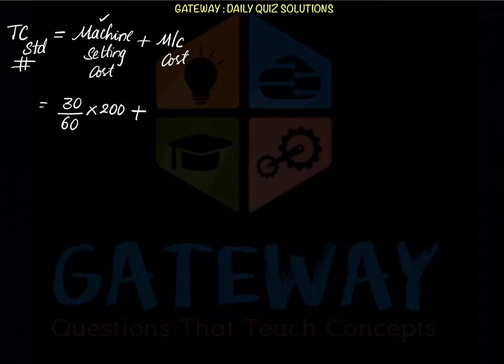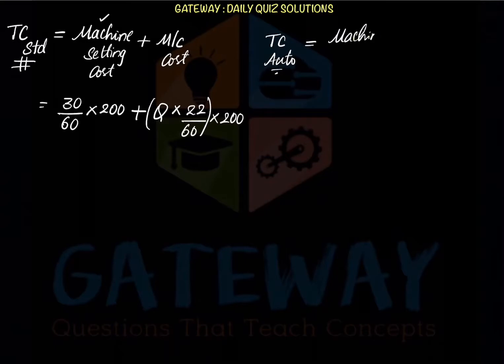And also the machining cost: for producing q number of components, each component we are told takes 22 minutes, nothing but 22 upon 60. For this total time, we need to pay rupees 200 per hour for the operator. This is the total cost for the standard, and the same for the automatic. I'm writing auto here for automatic. Here also we have the machine setting cost and also the machining cost.